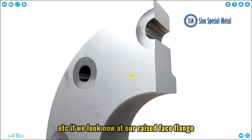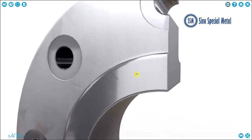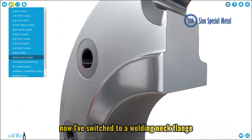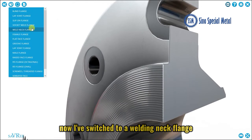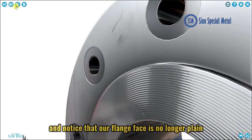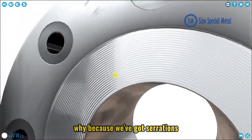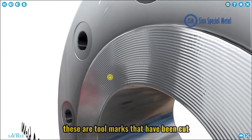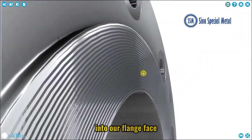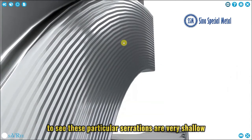If we look now at our raised face flange, you'll see again that we have this plain sealing surface, no tooling marks. Now I've switched to a welding neck flange and notice that our flange face is no longer plain, it's no longer flat. Why? Because we've got serrations. These are tool marks that have been cut into our flange face. If we take a cross section, it might be a bit easier to see.